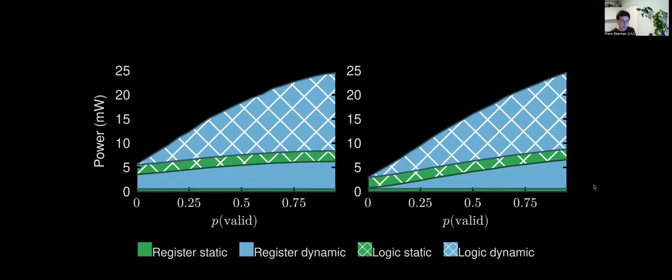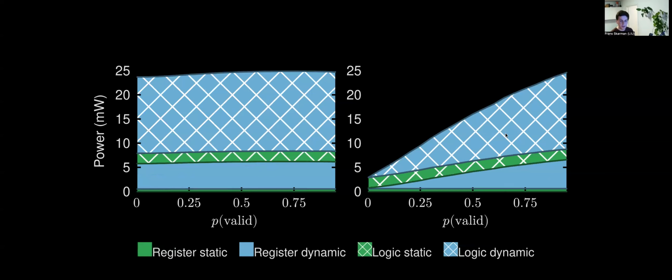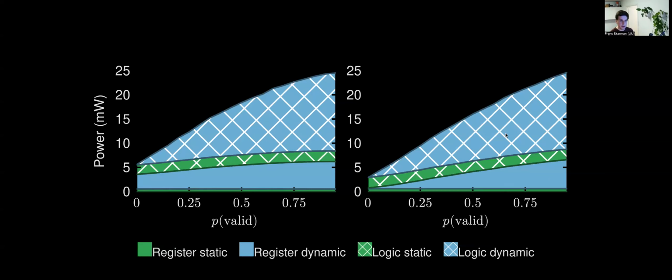Of course, you could apply this optimization manually, but that requires writing all of your registers like this, which would be super tedious. It also means that if your assumptions about your application are wrong, so maybe you thought you were in this scenario, but you're actually in this scenario, then you have to go through and change all the registers. With an optimization, we can enable design space exploration and change things depending on the application and the input.